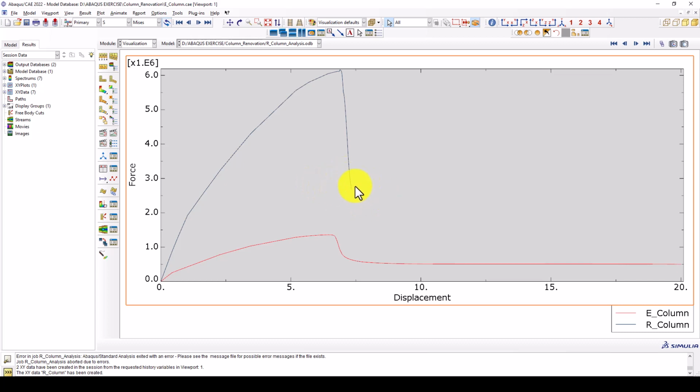That's the problem. In case you want to continue to see 20 millimeter deformation, it's not a difficult job. You can allow the program to change the analysis type to dynamic, and it will converge. Or also change the attempt parameters, which we already discussed, and it will reach this one. But for me, because my main point was the gap, how much that retrofitted part can affect or impact the structure, we can see it's quite large, in the strength alone.